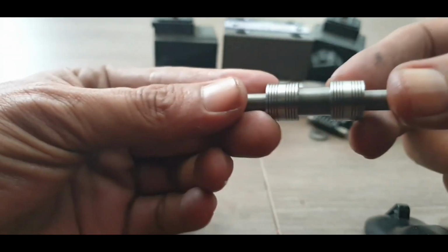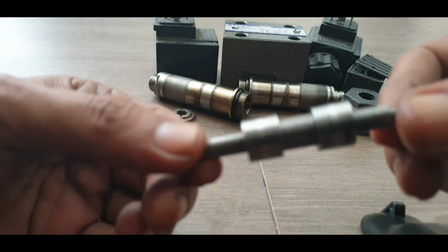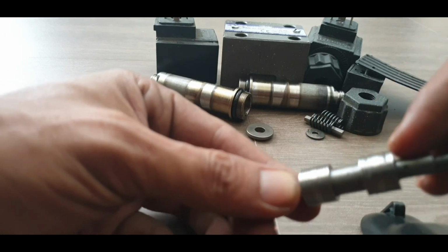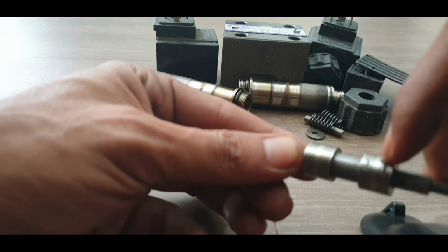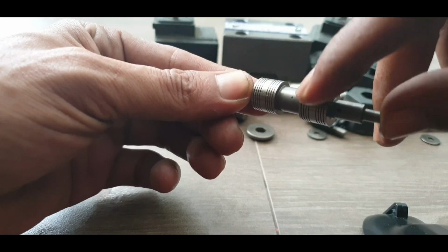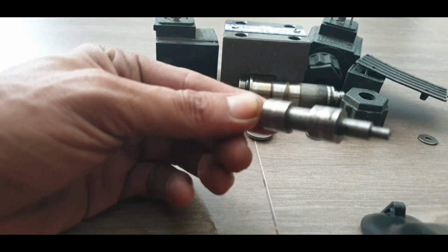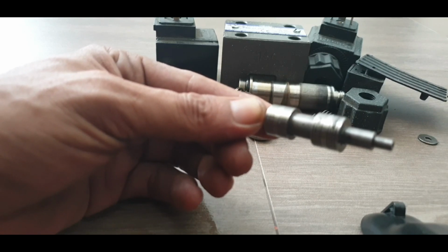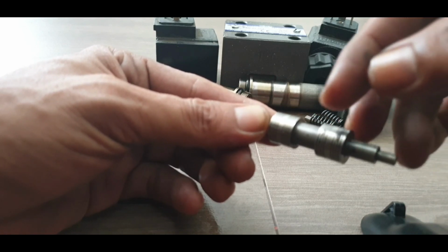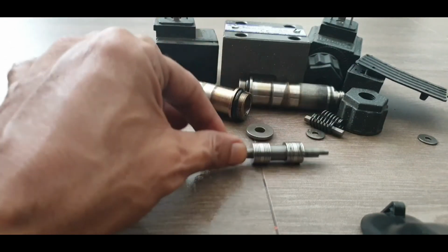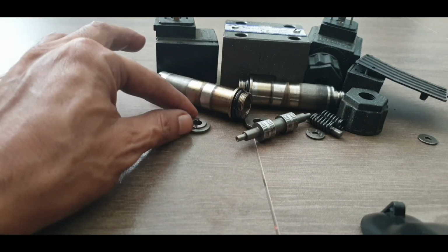And then this spool, if I zoom in, maybe you can notice some scratches already here, some scratches here. If your fluid mechanism has no power to lift, the main reason may be that there is a scratch here. That is one reason, other reasons you have to investigate, but at least you can understand the mechanism, and then I believe you can solve the problem more easily.